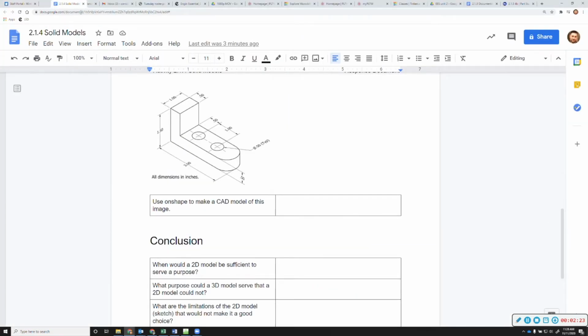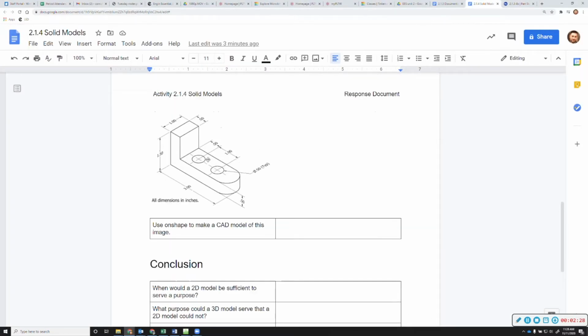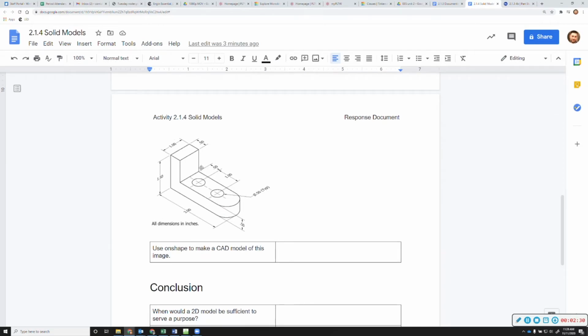Okay, so actually, you know, let's just put it back over here. I'm going back and forth anyway. So if we look at this shape, I have to take out a piece that's inside half an inch and then down 1 inch. I know it's down 1 inch because this whole thing's 1.5 inches tall, and this piece right here is half an inch tall. We see that from here. So I need to go down 1 inch because 1.5 minus half is 1. So I need to go over half, down 1, and then kind of cut out that chunk.